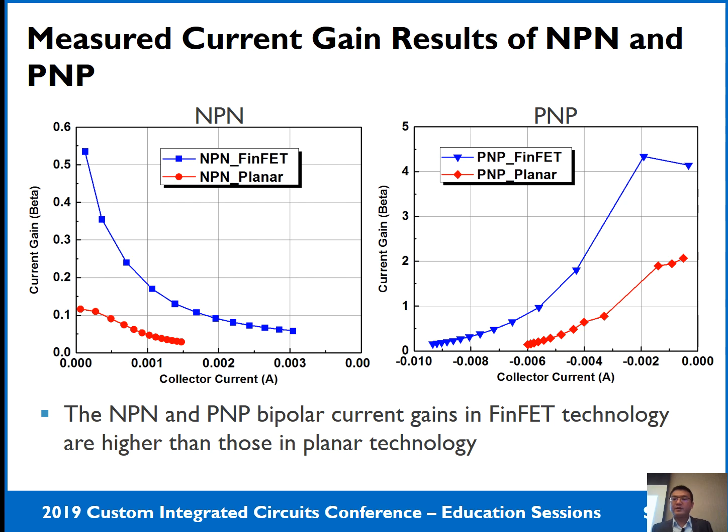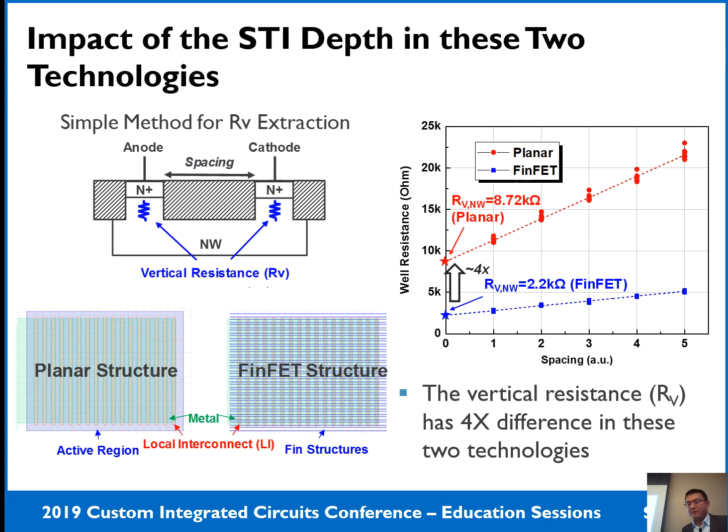This can be further proved by illustrating the vertical resistance. From this measurement result, we can see that this vertical resistance is 4 times higher in the planar technology, which means your STI depth is much deeper in the planar technology.